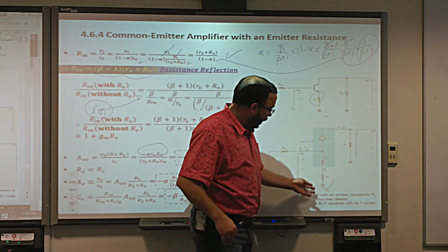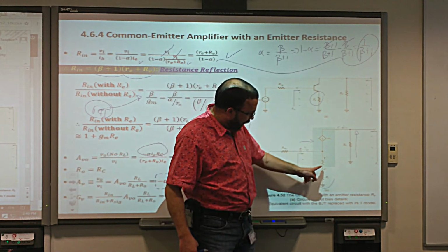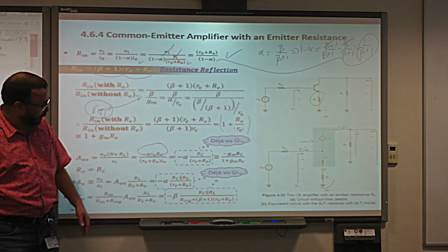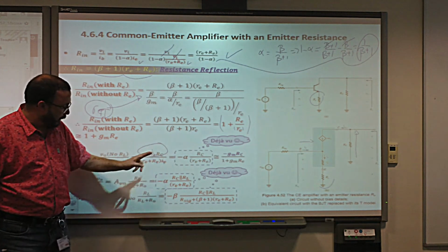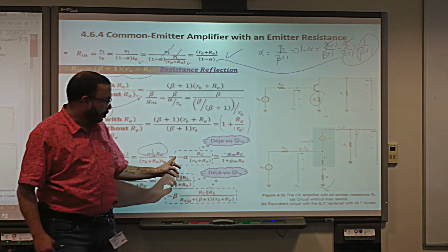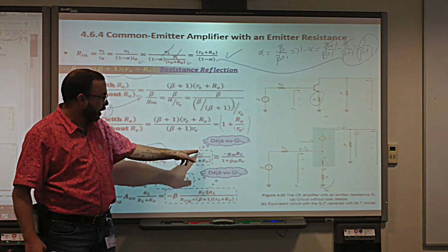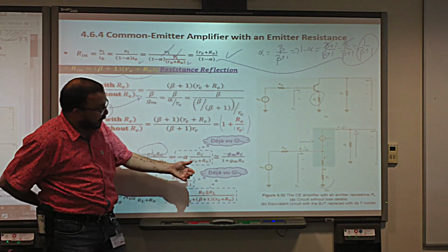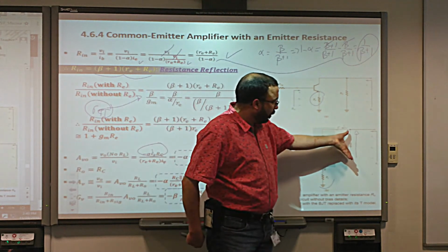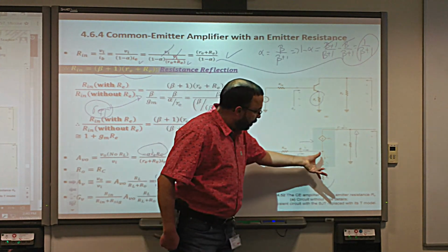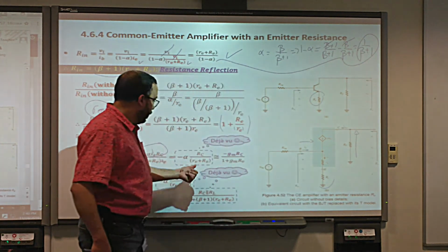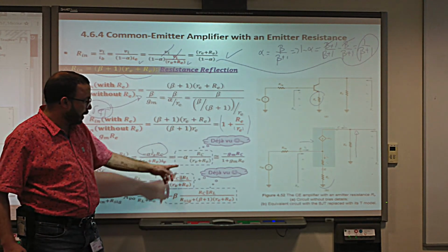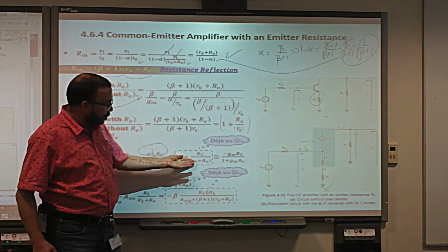Again, the input voltage in here is going to be equal almost to this current IE times these two resistances in series. And then IE gets cancelled, and we get minus alpha RC divided by these two. And again, here we have an interesting thing. You can see that the collector resistance is only RC, divided by the emitter resistance, which is small re and capital RE. Exactly the same formula that we had before. And that's it. We can simplify this equation to get this.